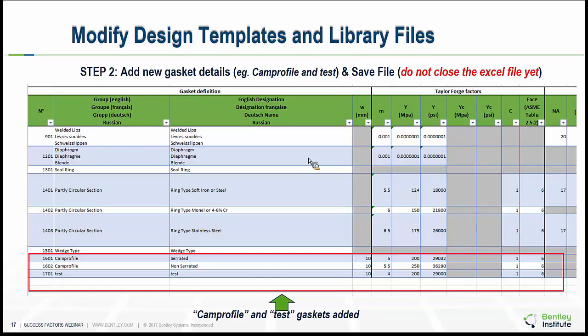Okay. Yes. How many customizable cost estimation configuration files can be created? There's no limit. You can create as many cost estimation configuration files. It's just simple copy paste option. So you can create as many as you want. One thing you do need to make sure is that you select the right unit. So either it's US or SI. That's dangerous if you don't pay attention to. So you have to be careful about which cost estimation file you copy, whether it's the US one or SI one.